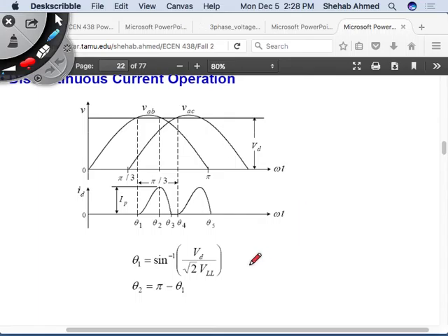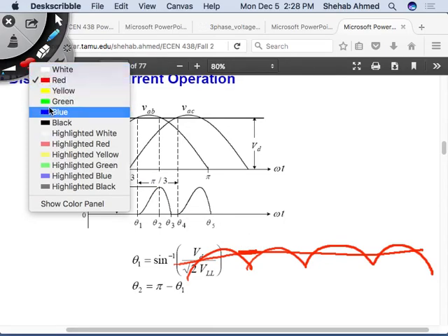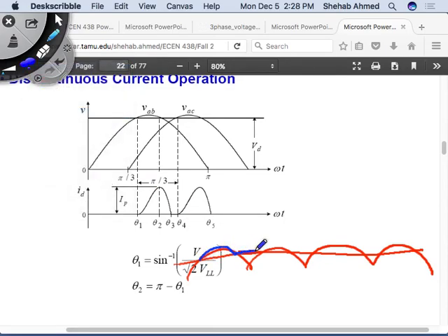You have this 6 pulse coming from your 3-phase rectifier, and then you had a DC source. At these places where the DC source is high, the current decreased considerably. So assuming that the current was 0, the output will look like this, here, like this, here. Since there's no current, then the output voltage will be the DC source, right? So instead of following the input, right?